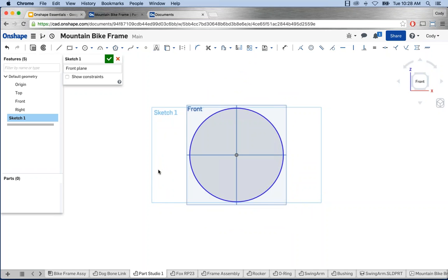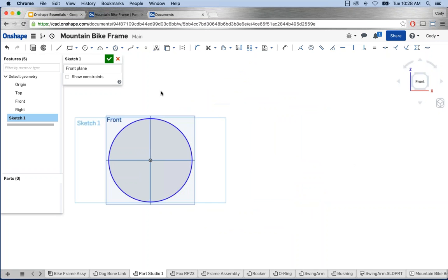But our goal, like in many of the traditional CAD applications, is to have a fully defined sketch that's completely black. Right? So let's move on. Now I have my first circle in place. We're going to do that one more time. Circle. I'm going to use a horizontal constraint to the origin. So again, notice as I move my cursor up, I get that reference to the origin. Right? A horizontal constraint, left click, and I have a second circle. Okay. Again, I'll use the escape key to escape out of that.